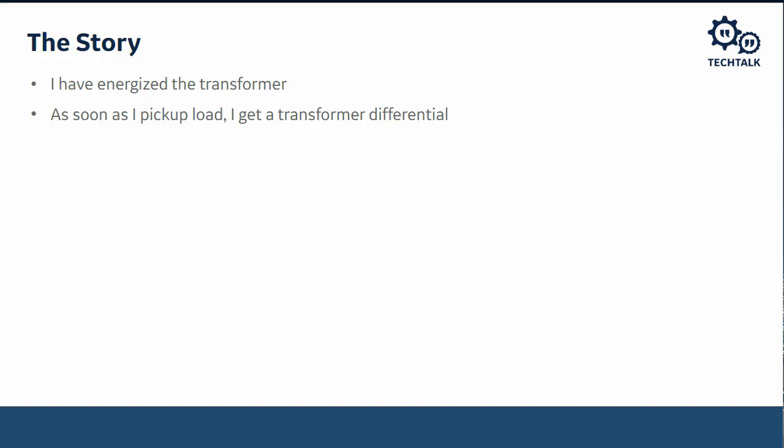So when did the problem start? Well, this is sort of a new installation, so every way we can think of this, it has been there since the install. Is there a way that we can isolate the problem to as small of an area as possible? That's going to be something I'm going to focus on in my troubleshooting and my event analysis. And also I want to make sure that I'm not jumping to any conclusions or trying on theories. But since we do have oscillography, we ought to be able to at least understand why the relay is operating. So let's take a look at that oscillography.